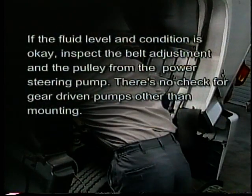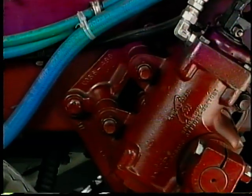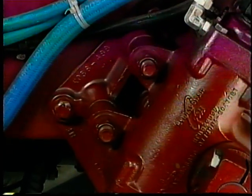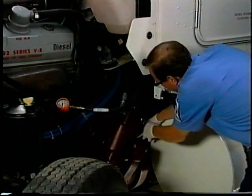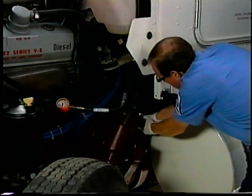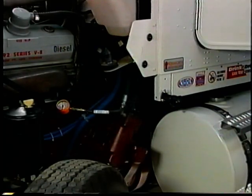If the fluid level and condition is okay, inspect the belt adjustment and the pulley from the power steering pump. There's no check for gear-driven pumps other than mounting. And don't overlook the mounting brackets and bolts that can come loose from vibration for both gear-driven or belt-driven steering pumps. Testing the hydraulic pressures in the power steering system requires the use of a power steering analyzer between the high-pressure hose and the steering gear.